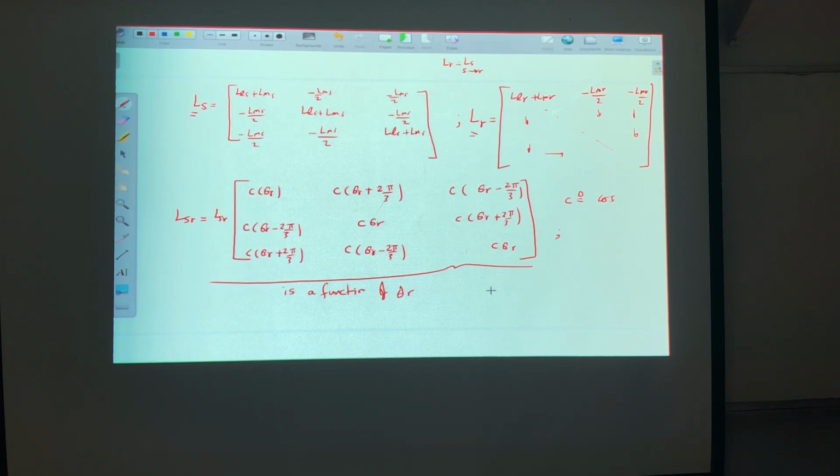Okay. Now it's preferred to write all the quantity referred to the stator, and to use LMS instead of LMR. We have a relation in between. So simply here we can say that LSR actually is equal to NR over NS LMS. The same thing I can do here.